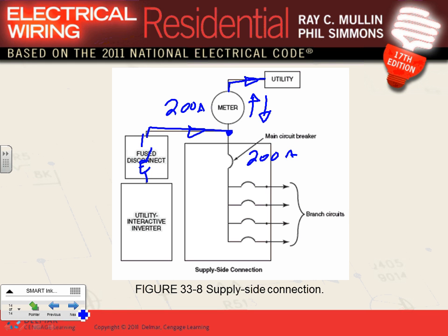The most important things. Now to summarize, if you want to get more voltage, what do you do to the panels? You have multiple panels. You put them in series to get more voltage. To get more current, you put the strings in parallel, right? And we know how to size them. We size the disconnect switches and everything else based on 1.25 times the full load current of the string plus another 1.25. If you guys add this one to your reservoir of knowledge, you will be much better designers. Some of you might be drafters for the rest of your life and you don't have to worry about this one. It really depends what you're going to be doing. Cool? Okay, that's all what I have for you.